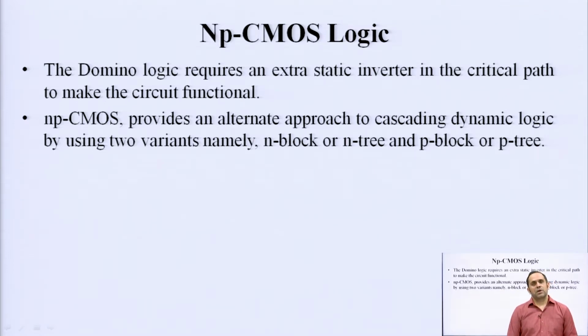So, for all these reasons, the complementary nature of N channel and P channel devices is what is generally used, or we can say exploited, to produce logic design circuits. Whether it was static CMOS, dynamic CMOS or domino logic design, all of these have used the complementary nature of N type devices and P type devices.